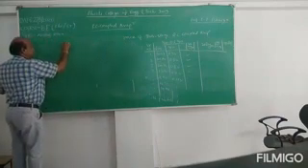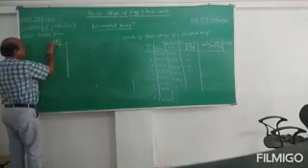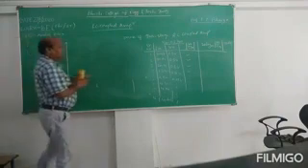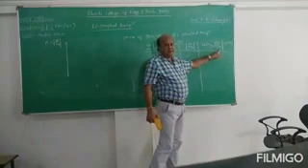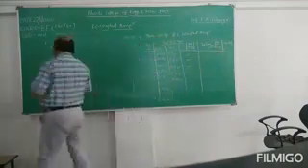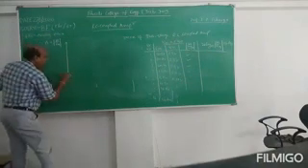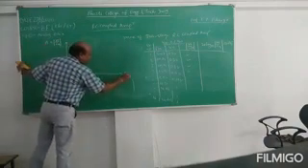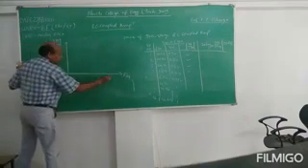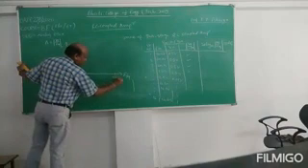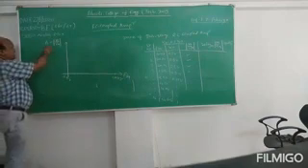Here, take the vertical axis as this gain, V naught upon V in. This is called gain. This gain either in this column or in dB. If you take dB, there will be a change in dB here, or if you take the ratio, there will be a maximum value of ratio. And in the horizontal axis, you take this frequency, F in, input frequency. This frequency will start from 0 Hz and go up to 1 megahertz.